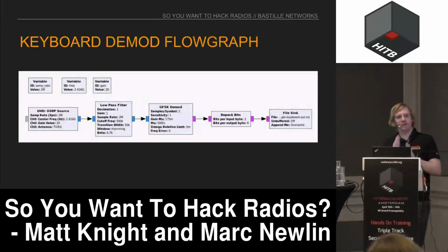So now that we know that these devices are transmitting on a single channel, and we know the modulation type, we can start to demodulate the data and see what bits we get out. The problem is, because we only really care about what the keyboard is transmitting, we first need to figure out what the dongle is transmitting so we can ignore that.